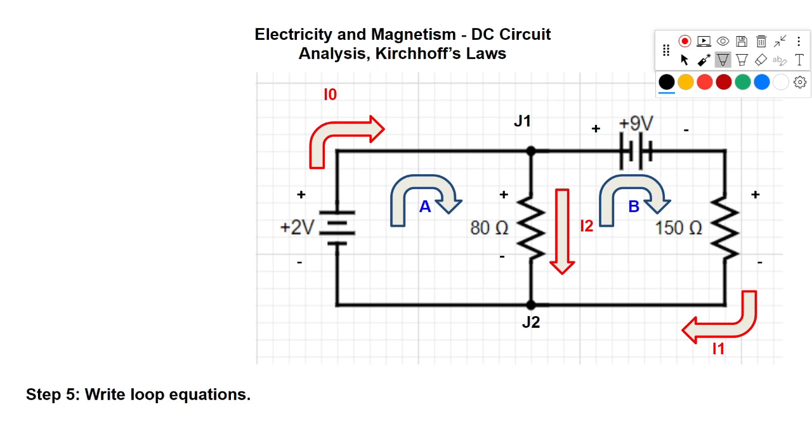And to do this, we're going to need some conventions. So let's look at what we have here. If we have a resistor, and our loop path is entering, and it's going from negative to positive, we're going to say that this is a positive uptick in voltage. And by the same practice, if we have our loop coming in and we have a voltage source, and I'm going to draw it a little bit simpler, and here's our loop, it's coming in, and again, that's going from negative to positive, we'll say that that is also a positive voltage.